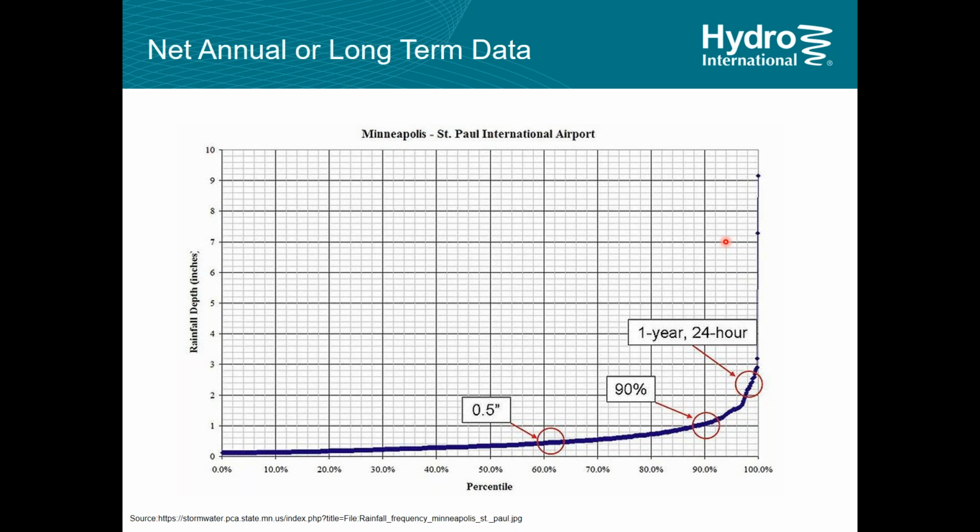I see the wording must be designed on a long-term average basis or a long-term rainfall basis, and what that really means is that you take a rainfall record of several years or decades and you sort that record into different intensities. So over a long period, say 10% of the rainfall is of a very low intensity and so forth, and it builds up.